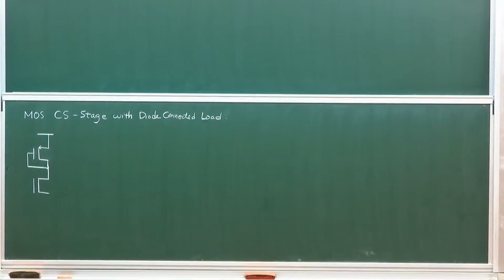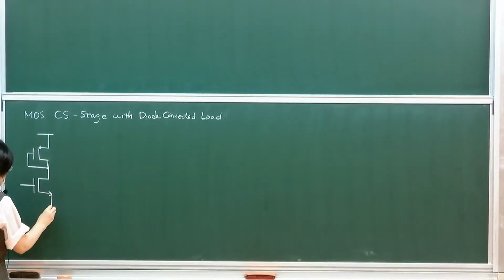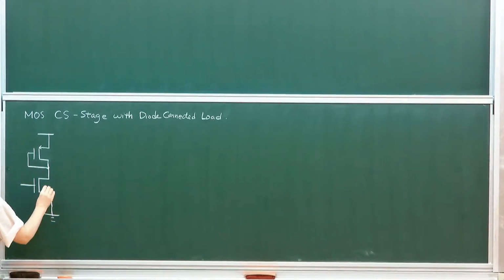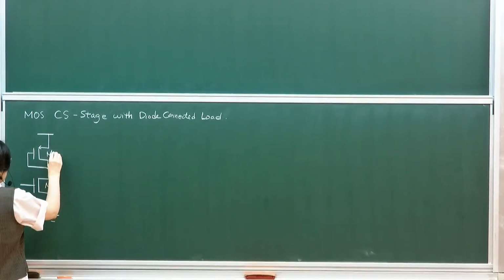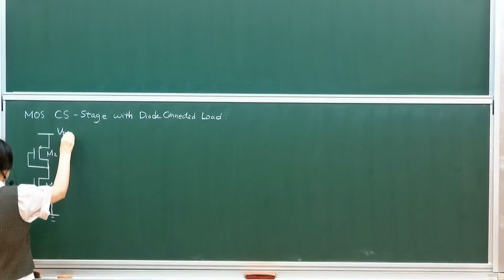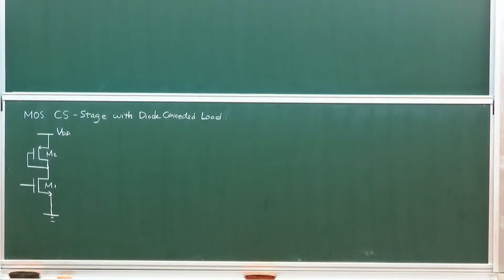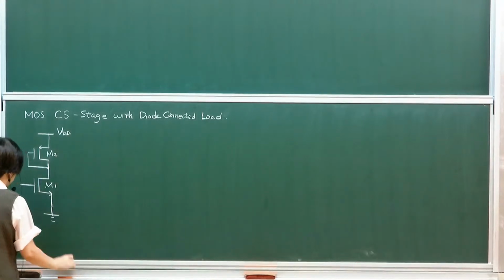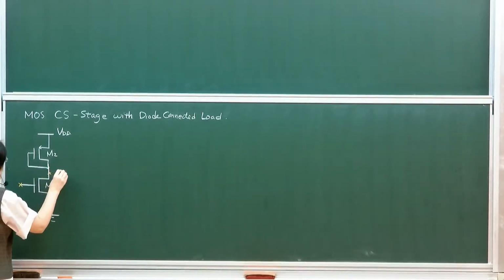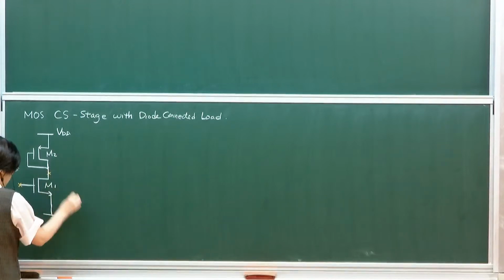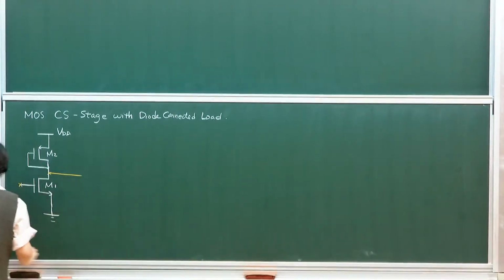You can do it in various ways. We can do it with NMOS diode connected or PMOS diode connected. I'm going to do a PMOS version with the diode connected. So if this is the case, if you simply bring in the parasitic capacitance, you can also ask to find omega P1 and P2. So I have output, let me do the same plot.